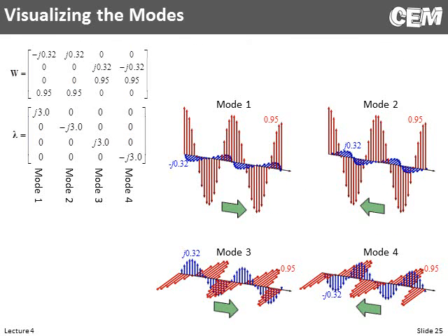So here's, as best as I can come up with, a picture of that. We have 4 columns in W, meaning that there's 4 modes. So there's actually only 2 modes, but we have 2 of them going forward and 2 of them going back. And why are there 2 modes? Because there's an X and a Y direction. We can have two polarizations. So 2 modes, but we actually have 4 because there's 2 forward, 2 backward.